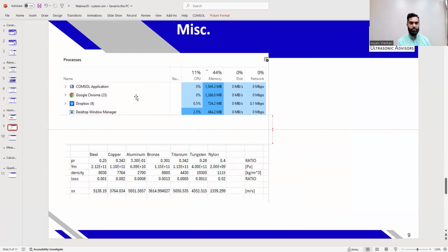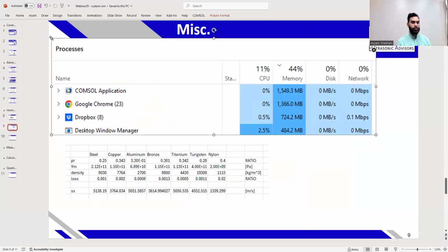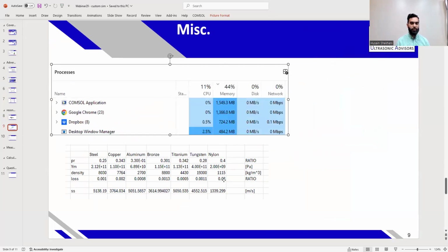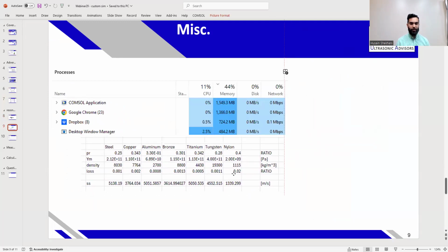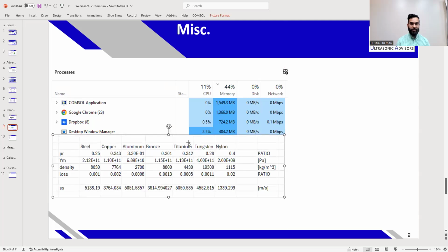And here are some things to note. I'm not telling engineers something they don't know, but you can go in your task manager to see how much RAM they're taking. COMSOL itself also doesn't tell you how much RAM it's going to take before it goes ahead and does it. So you've got to be RAM careful, RAM conscious. We're all encouraging all of our friends to be RAM conscious when doing simulations, or else they might take forever, right?